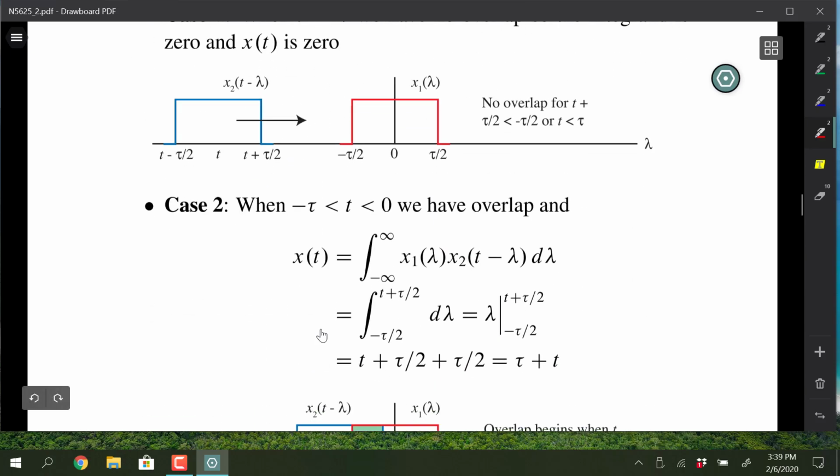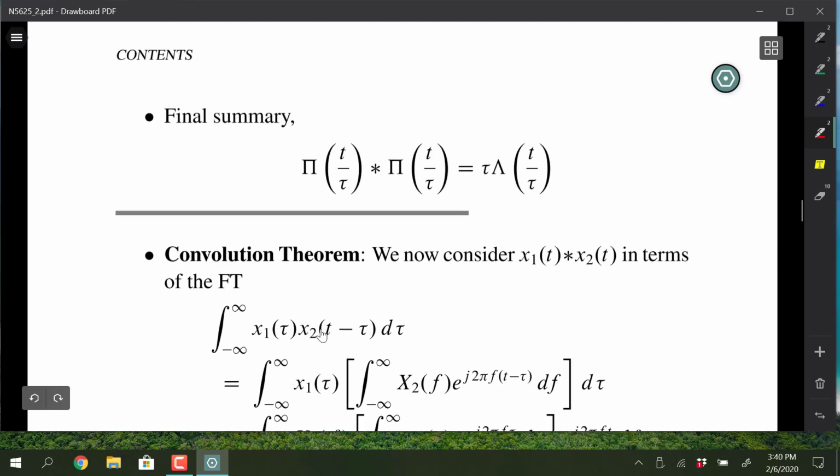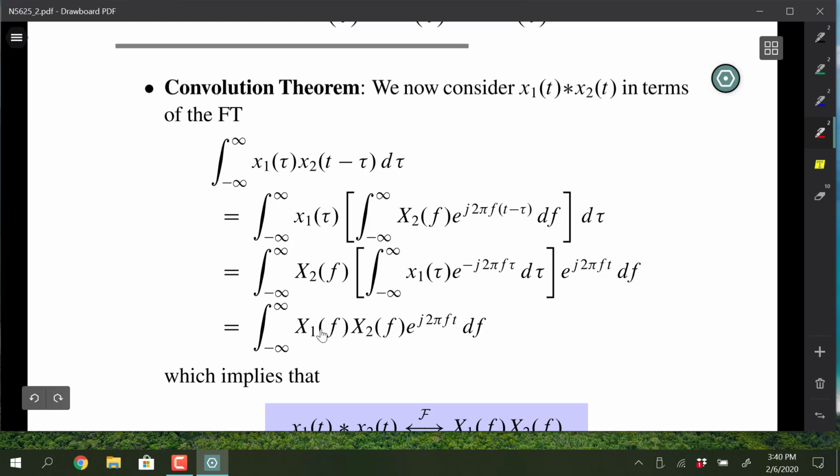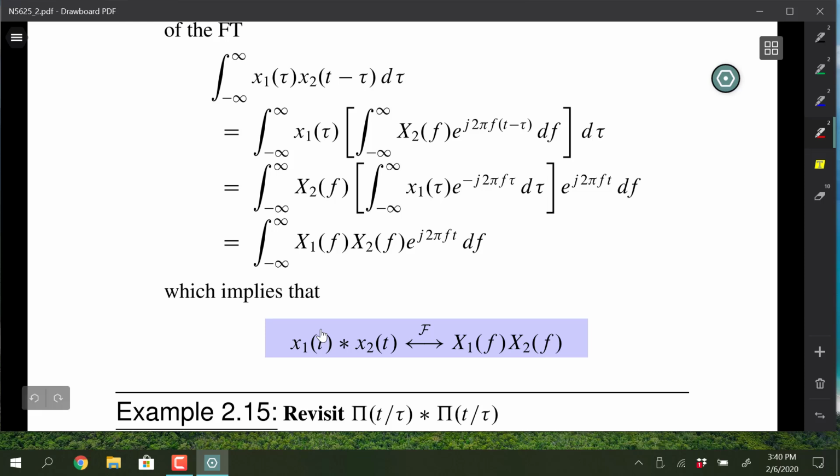So I did put this example in. We talked about the results of this one. Then this is the convolution theorem, which follows from understanding what convolution is, just saying that when you convolve in the time domain, you multiply in the frequency domain. And that is very powerful, and it shows up a lot in comm systems. If you really want to get intense about getting back to the time domain again, you're better off working in the S domain, though, because then you can use the Laplace transform, the inverse transform, when you want to get back to the time domain.